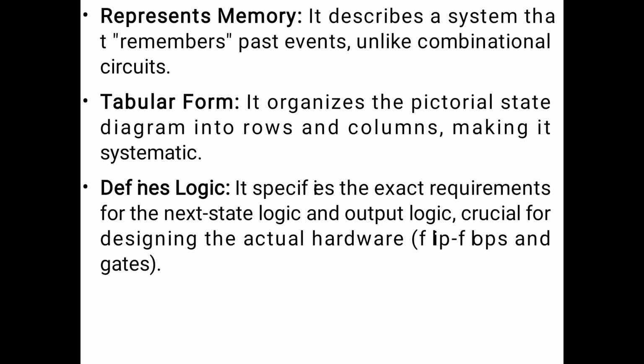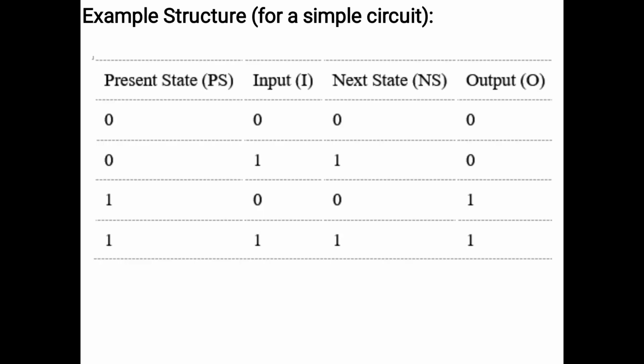And the state table specifies the exact requirements for the next state logic and output logic and is crucial for designing the actual hardware which we require. That is, we can determine the number of hardware requirements, that is the number of flip-flops and gates needed, with the help of the state table.